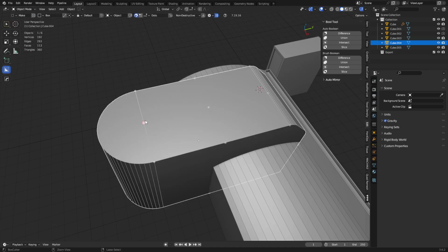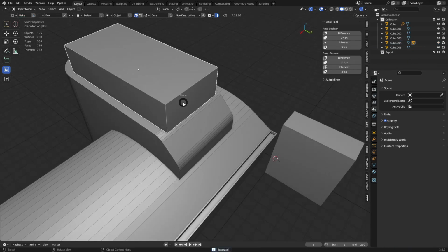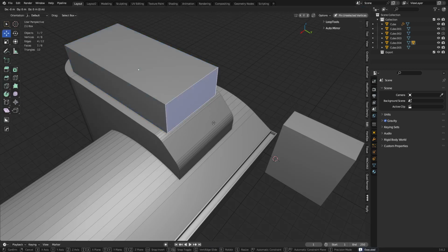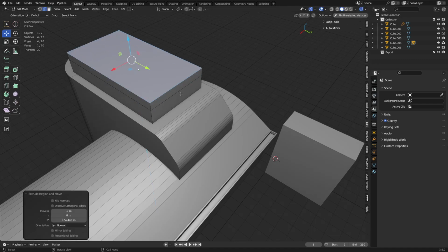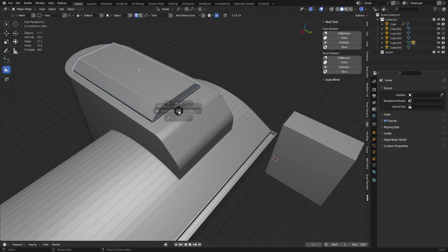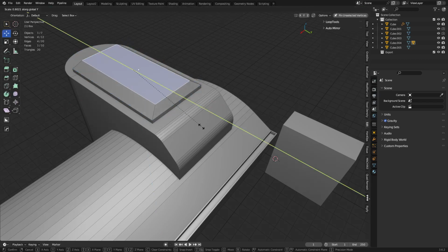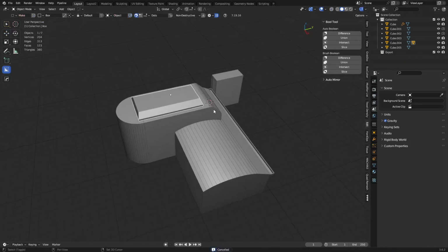We can't do like a Control and Shift clicking, unfortunately, but we can just draw from somewhere and hold Alt. Do a number like this, bring it up. You see it goes out in both directions unless you unselect Alt. And now you go through and do that. So I can grab this later, pull it forward, adjust it. Maybe we extrude it a little, scale it in this way, bring the whole thing down. All right, so we got something like that going now. All kinds of little fun adjustments we can make. So yeah, box cutter is extremely useful.